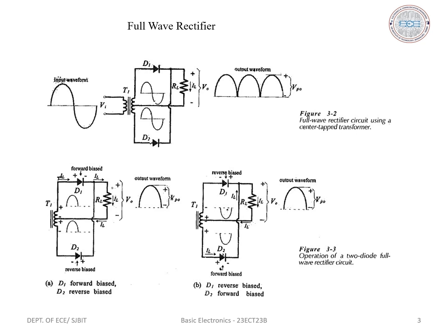So let us see how it is going to work. During the positive half cycle of the AC supply, that is when we send the positive half cycle of the sinusoidal signal to the full wave rectifier, the voltage at point A is positive and point B is negative. Point A represents the anode point of D1 and point B represents the anode point of D2. Therefore diode D1 conducts as it is forward biased, and D2 is reverse biased, remaining in off state.